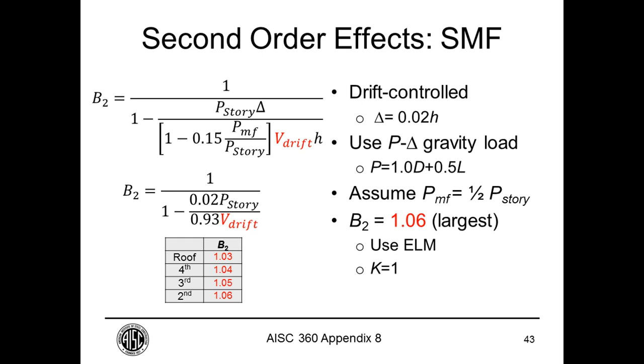And the question is this: there is this load combination that you show here with a 1.0 for the factor for dead. Can you explain where this load combination is used in comparison to the load combinations used later in the presentation with higher load factors? Yes, so this is an interpretation. For strength design, the standard load combination would include 1.2 dead plus 0.5 live and so on.